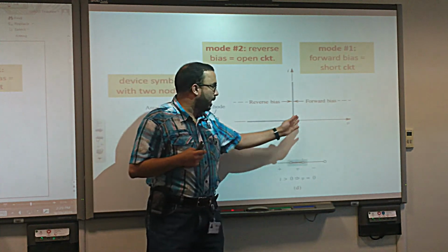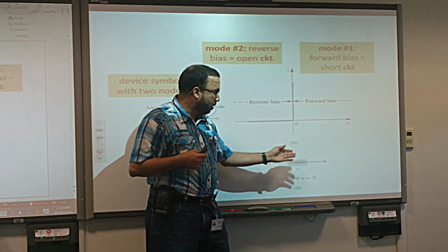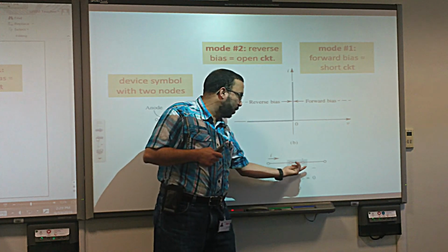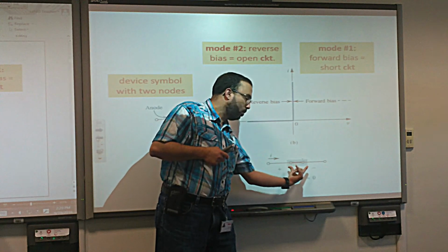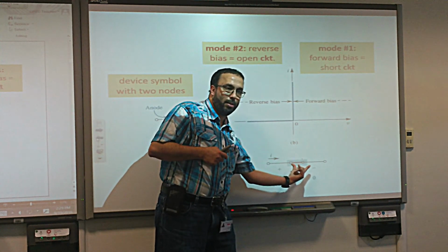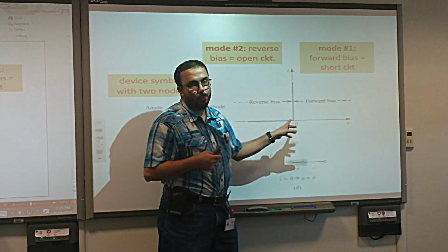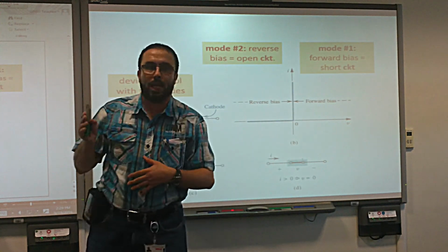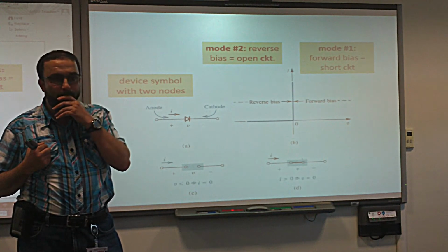That means here, what does it mean? It means for the diode in the forward bias, any current you pass, still you will not have much voltage drop. It's always V equal to 0 between the two terminals of the diode. Do you understand? Because the resistance is 0, and that's why it's like this. So like we said in the movie, if you remember, I put also those movies in the blackboard.